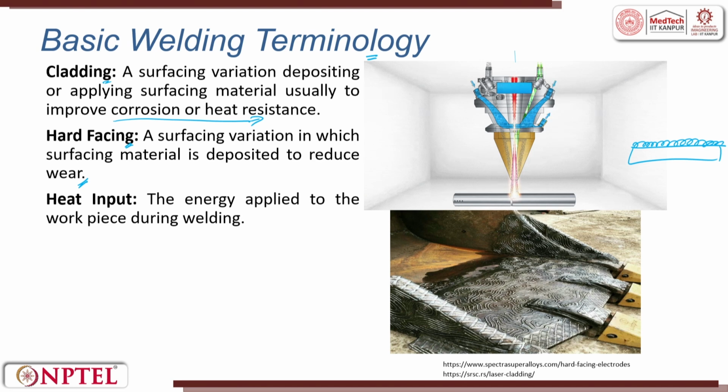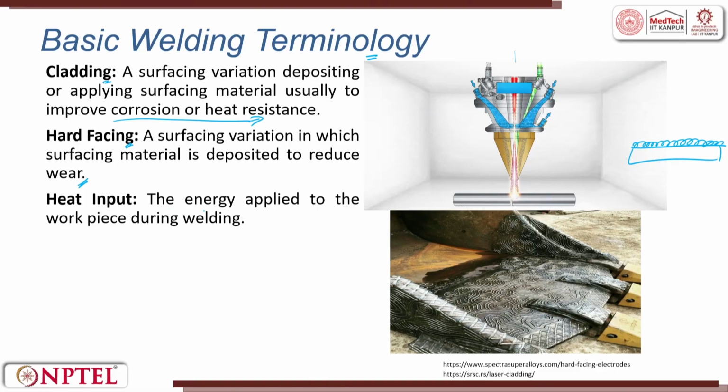We also saw cladding in the forging process, where a complete sheet will be clad with another sheet, joining them; that is cladding. Here it is powder cladding. You can do it by plasma, oxyacetylene can be used, or even explosion can be thought of. The heat input is the energy applied to the workpiece during welding.